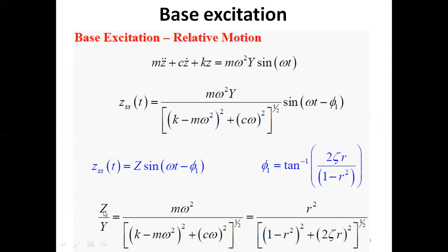So here on both sides, numerator and denominator, we have displacement. So again, this is a displacement transmissibility, but now in terms of the relative displacement. And here we could see the frequency ratio and damping ratio. So we have a completely dimensionless equation.